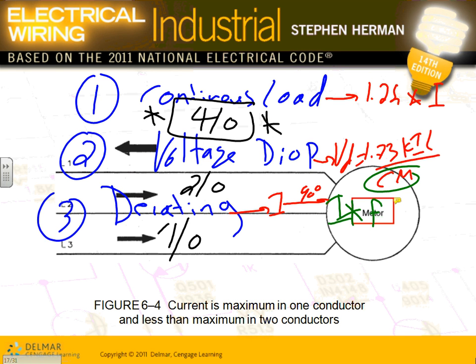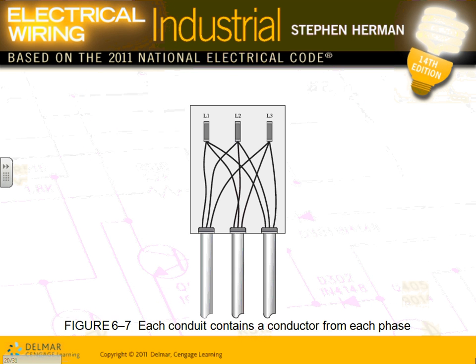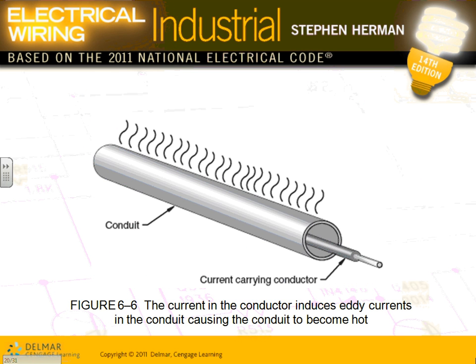Okay. So the rating, you pick the largest. And we'll talk about this one, guys. Parallel conductors, we talked about the rules for parallel conductors. When you parallel conductors, you put them in the same conduit because of induction heat. Medium voltage, you are allowed to put them in ducts underground, but in close proximity to each other.